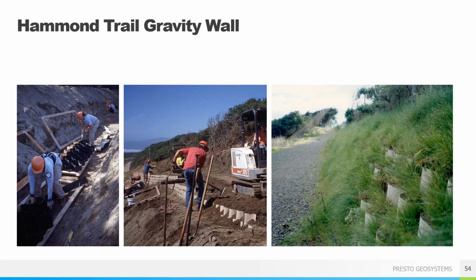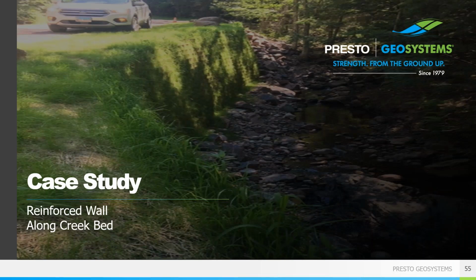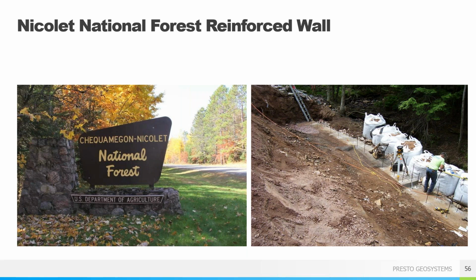It's pretty easy to design a gravity wall. I mean, they are functional and they are great walls. Like I said, they do have limitations with heavy surcharges. I'm sure we've all seen gravity walls that over time have slid. They don't have any back reinforcement. So a lot of times, like I said, if there's going to be high surcharges, I'd like to do a reinforced wall versus a gravity wall. So with that, I'll do a reinforced wall.